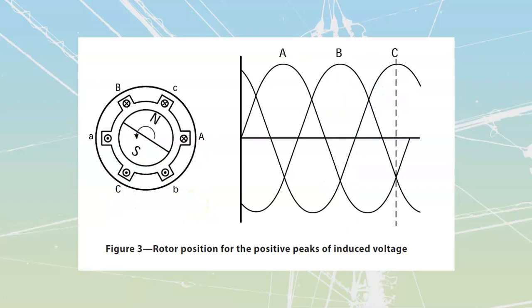And we carry that on into our third position that they show over here, which is where C is peaking. And I see that my C is peaking once again when I have got my pole lined up with the winding over here. And it's therefore going to be lined up with my winding on the opposite side as well. So we are going to have a C peak off of, once again, beta, length, and velocity over here. All of that ties together. We get those high values of voltage right now on the C winding, and we see that A and B are going to have a smaller value of voltage in the opposite direction over here.